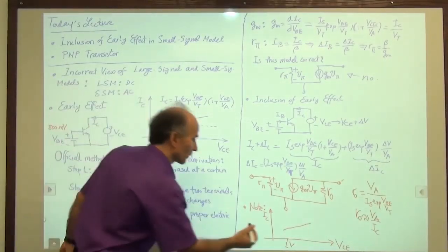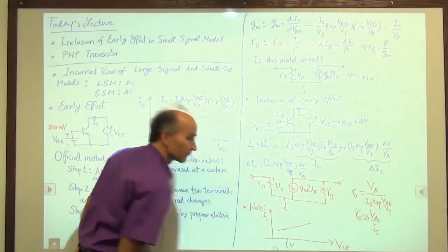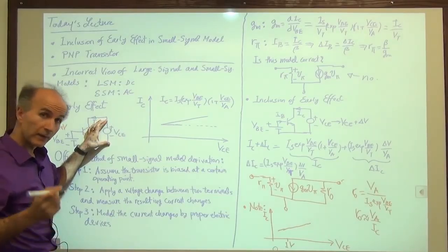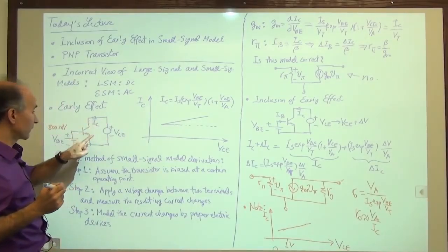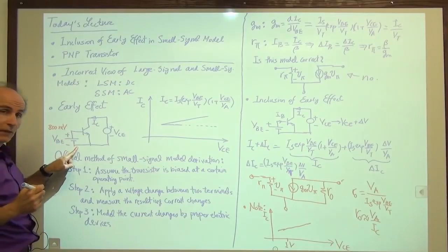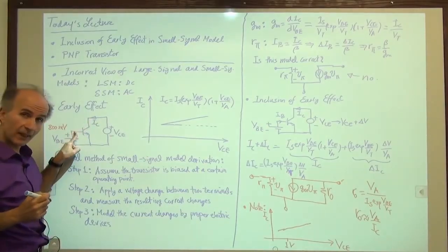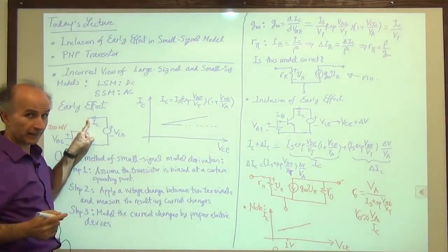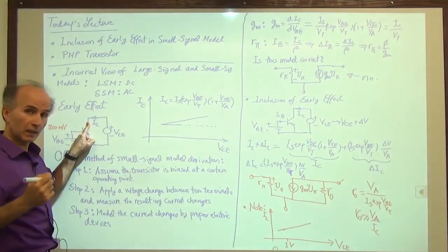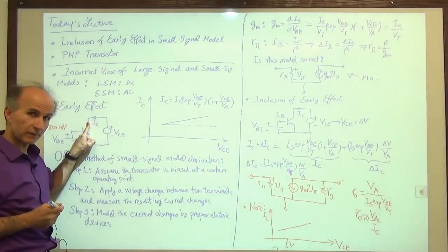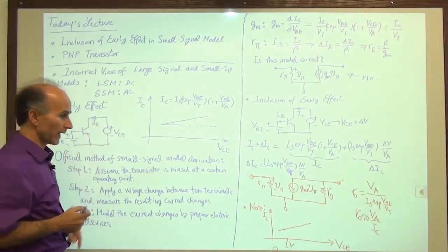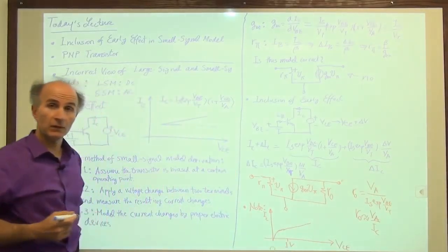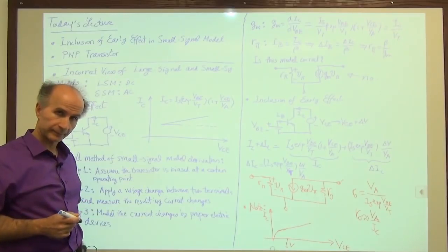But now we come down even more. For example, this comes down to 500 millivolts. If this is 500 and this is 800, the collector is less than the base, so the base collector junction is forward biased. And that's not what we would accept in forward active region. If we keep doing this, suddenly the collector current falls, and when VC goes to 0, it goes to 0.